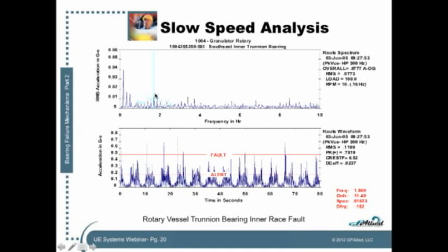So even without looking up the bearing number, your good vibration analyst is able to determine whether or not it was inner or outer race, if that's pertinent to the situation. Most people don't really care if it's inner or outer race. They just want to know if it's bad so they can get it changed, which I think is the right attitude to the whole thing. All right.